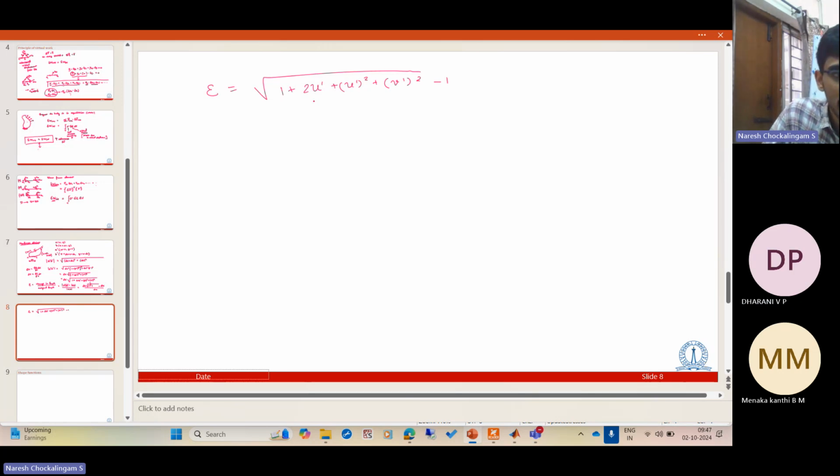Now, what we'll be looking at in this workshop is something called second order analysis. There are various levels of nonlinear analysis that we can carry out. The usual linear elastic analysis that we study in structural analysis is a first order analysis. So there is no nonlinearity. We consider the deformed shape to be the same as undeformed. So that's a first order structural analysis. What we'll be doing now is a second order nonlinear structural analysis.